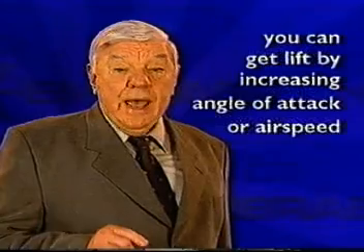Developing high sink rates is a unique problem and represents a potential hazard in jet aircraft. However, with a proper understanding of these considerations, neither one of these tasks is difficult. Remember that basically, you need more lift to get out of the increased rate of descent and go back to the proper flight path. And you can get lift by increasing angle of attack or airspeed. To increase angle of attack, your airspeed must be acceptable, or the extra pitch will take you to the backside of the drag curve, and the resulting sink rate will be higher.